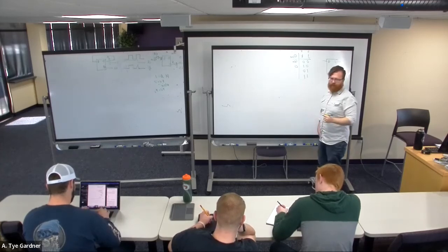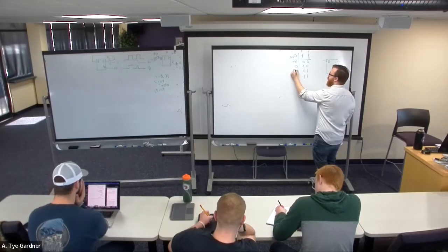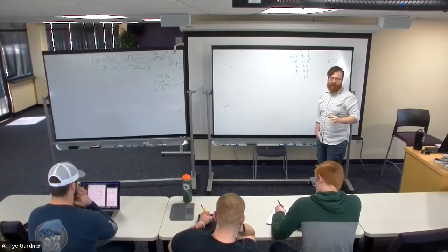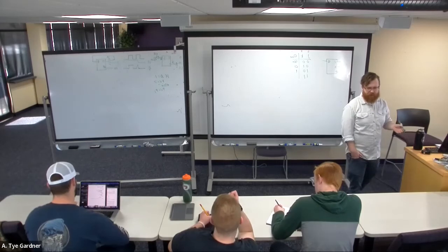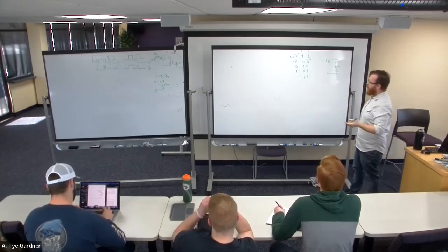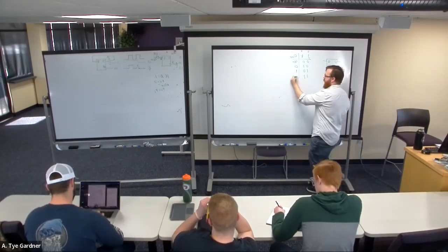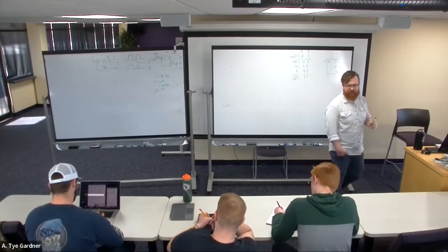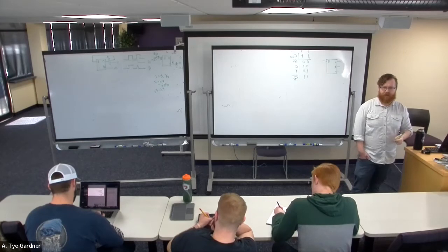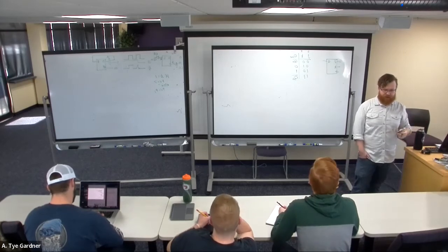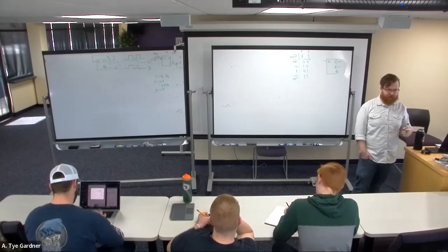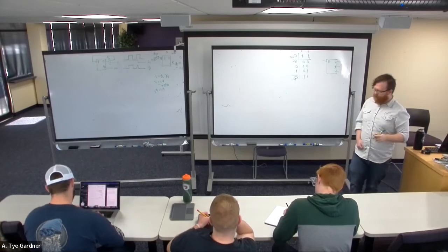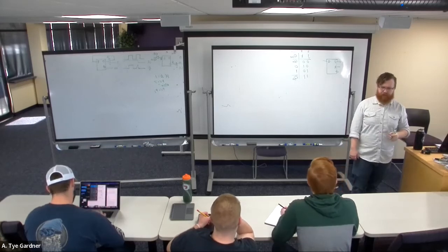Reset on K, set on J, but then it gives us something to do with the 1, 1, which is rather than it's bad, it inverts. Whatever, if Q used to be 1 and I put 1, 1 on my JK, I get 0. It inverts.